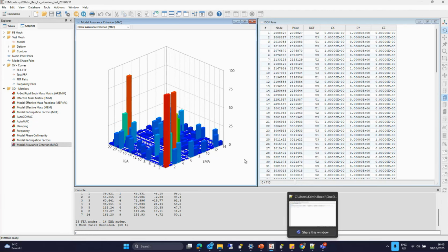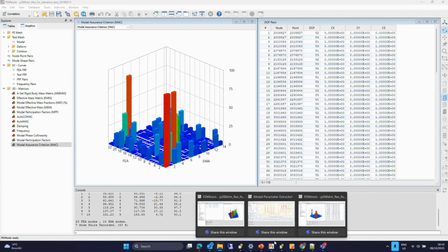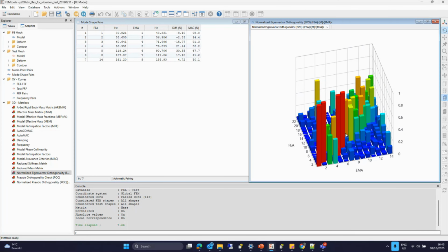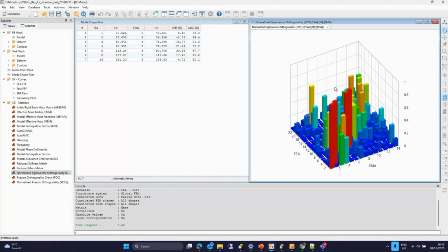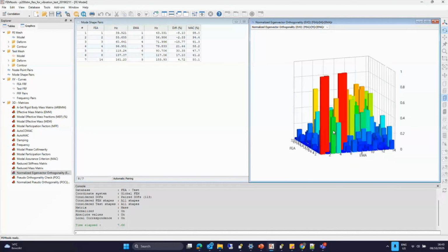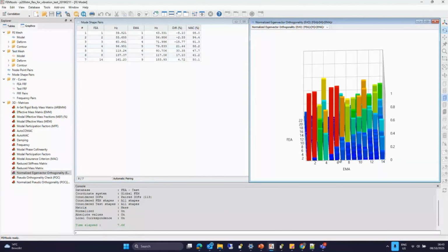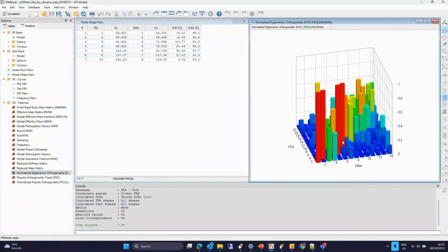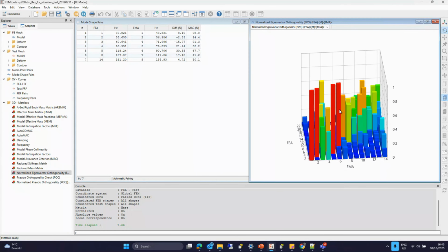But the EVO, on the other hand, does not assume mass distribution, because if you remember from the FE model that I showed, the tank is modeled as a lumped mass. So we have a concentrated mass in the middle of the satellite. The EVO does a good job showcasing this local mode, so we get a very good correlation here, or a better correlation compared to the MAC.